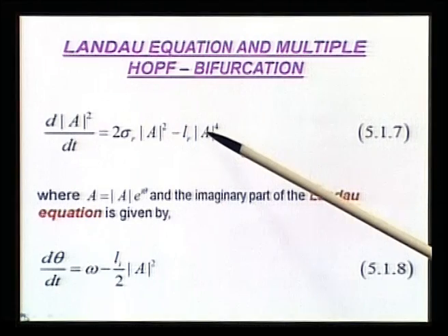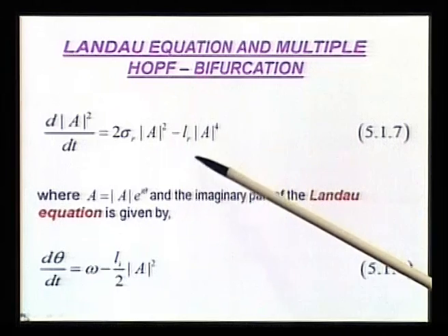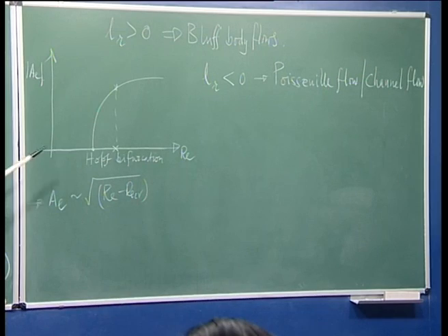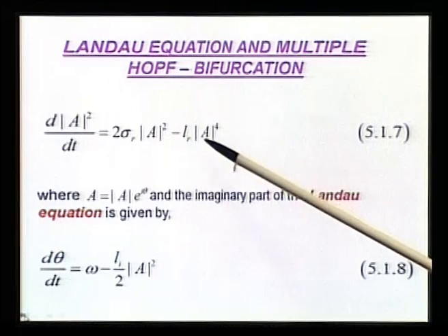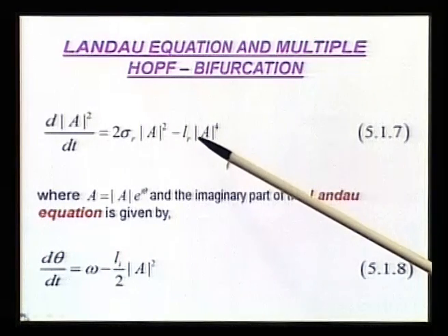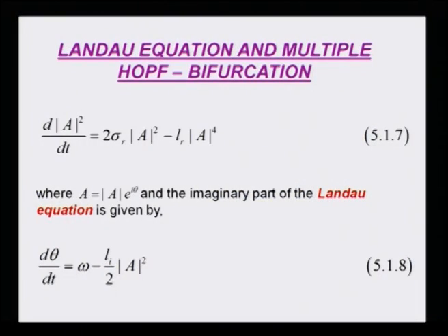The nonlinearity is causing a stable amplitude, helping you get a stable amplitude, and that is your Karman vortex shedding. Whereas, if I look at plane Poisson flow, LR is negative, and there we can talk about subcritical instability, right. So, this Landau equation is quite a nice model equation to explain both.